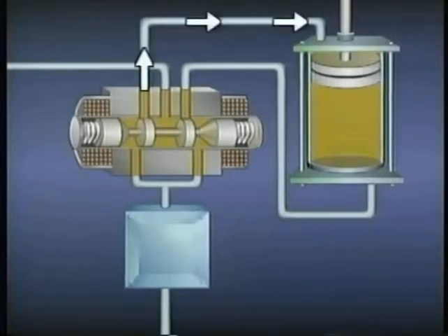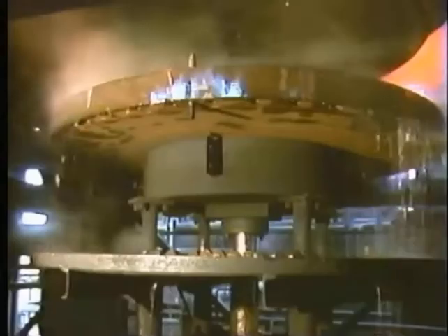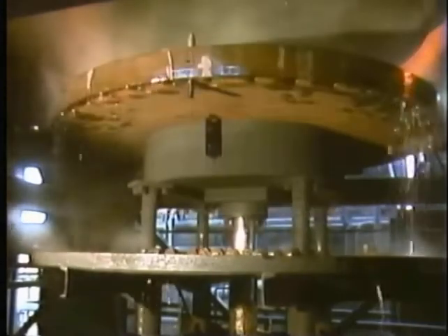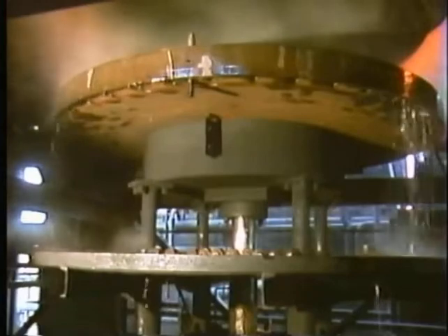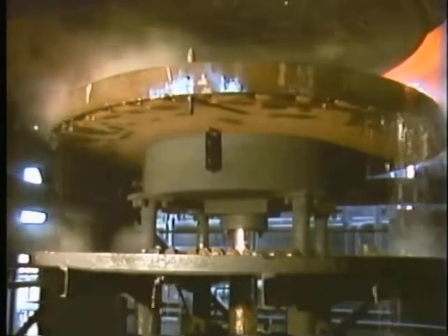When fluid flows to the upper end of the actuator, the action is reversed. Now the speed at which the piston retracts is controlled. So with a meter out arrangement, not only is the lifting of a heavy load controlled, lowering the load is also controlled so that it can't run away.